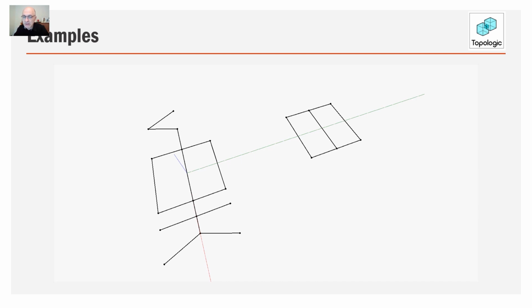But here is the first example, very simple. You try it on a very simple geometry just to make sure it works. So you'll see this shape on the left has some kind of extending lines, intersecting lines, and the script will clean them up and give you, actually, in what you see on the right is actually made out of three circuits. The two rectangles as well as the square that is the external boundary. And the script will give you all these separately so that you can deal with them separately.